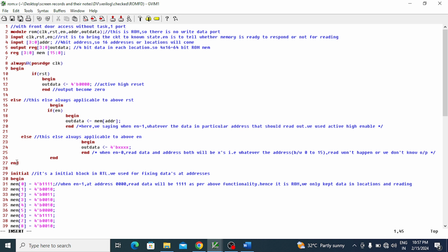Okay, in this design code itself I am using two procedural blocks. One is always, to code the functionality, and there is another procedural block that is not always, that is initial. I told in previous lectures we can use initial also in the design code. In previous lectures I have shown dollar monitor and display related in the design code. There I used an initial block. Now this is the second example. I am using an initial block.